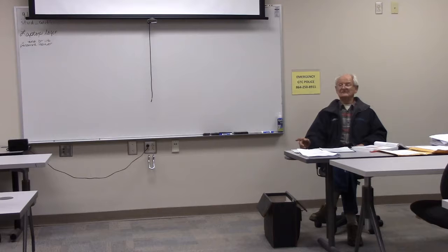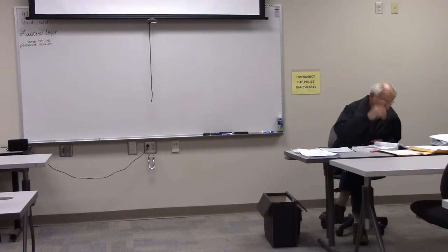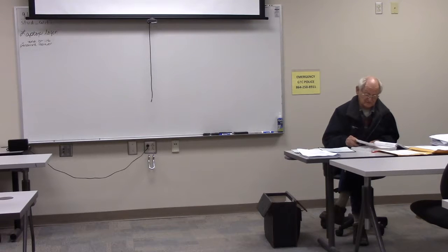In the kitchen, on the kitchen counter, you have to have two receptacle circuits, 20-amp receptacle circuits, and if they're within 6 feet of the sink, you gotta have a ground fault receptacle, or they gotta be backed up by a ground fault breaker. But remember that at least one receptacle is required in the laundry area.